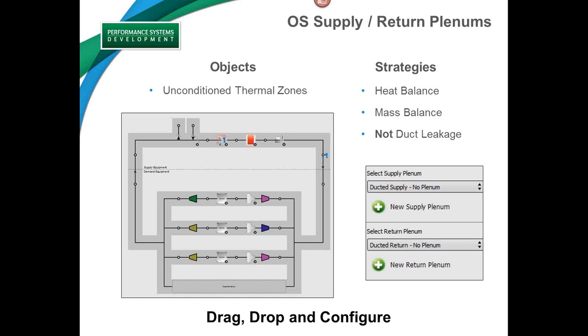You'll see the image at the bottom left here. The color codes describe common plenums. So we have, in this individual air loop, a purple or magenta supply plenum serving two different zones, and a sort of yellow or brownish yellow return plenum serving two different zones. So it's very flexible the way that this was implemented in OpenStudio. Plenums can certainly cross zones, or they could be one-to-one.